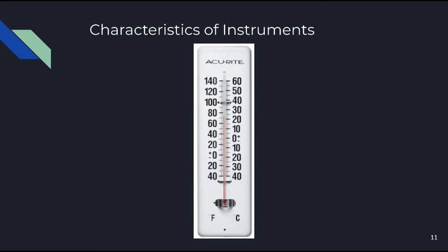If we had to measure the temperature of a certain chemical process, however, a variation of 0.5 C might have a significant effect on the rate of the reaction or even the products of a process. A measurement inaccuracy much less than 0.5 C is therefore clearly required. Accuracy of measurement is thus one consideration in the choice of instrument for a particular application. Other parameters such as sensitivity, linearity, and the reaction to ambient temperature changes are further considerations.